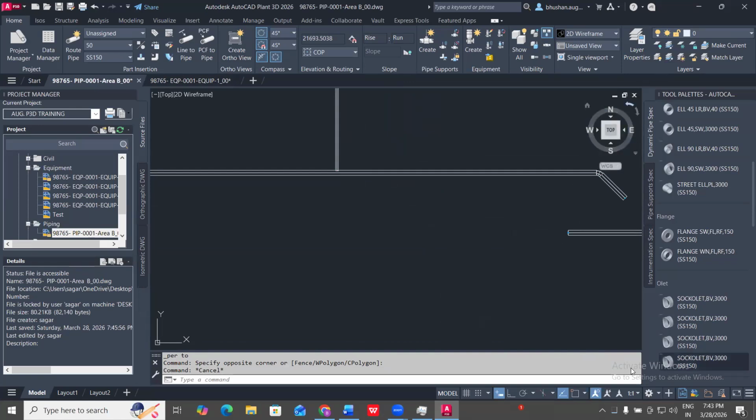And the fourth is a near point. So whenever you don't have a point and you want to find the point near to that object, you need to specify a point on the pipe center line, not on the end. So for that you also have the option of shift plus right click and select near, click anywhere on the pipe body or whatever component you are using.